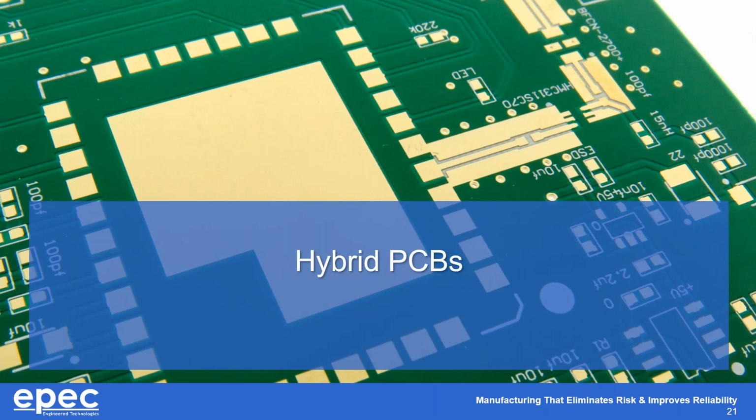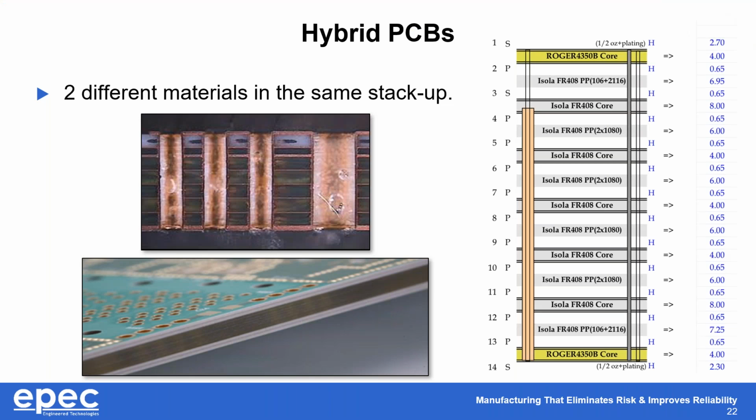So now we're going to talk a little bit about hybrid PCBs. The definition of hybrid PCBs is things that have two different materials in the same stack-up. It's pretty common now, especially in the RF world, when in an RF application there's a communication portion of it, to be able to put that portion on one end of the stack-up, very similar to the top one here, in order to only have one printed circuit board. That's pretty common. It's relatively easy to do.